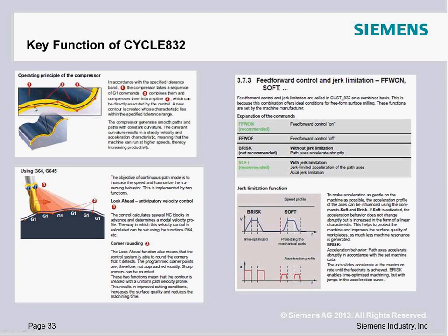It's really a value that gets passed from the CAM system, and it's really how far we allow the point that's being output in the part program to deviate from the original curve of the piece. So if you can, you want to use the same value that you're using over on the CAM side. It's going to make everything a little bit clearer. If you don't know what it is, use a standard rule of thumb, at least starting out.